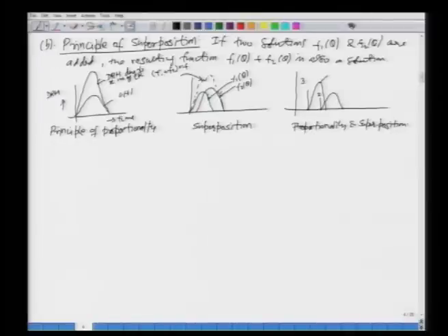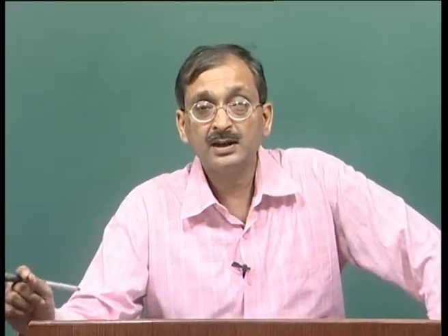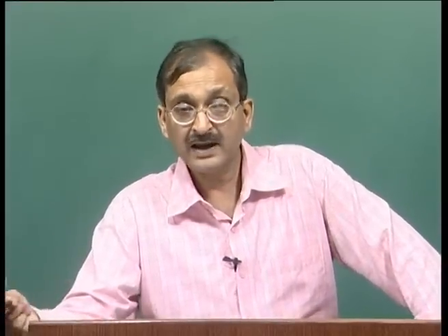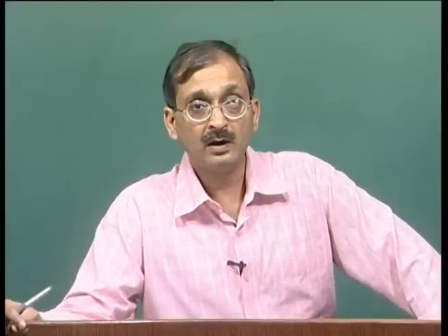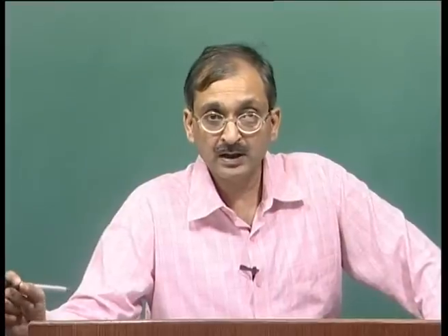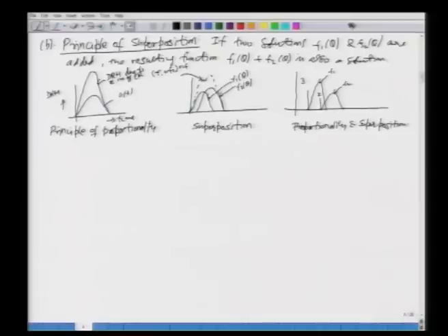So, now you have F1 and F2. What is F1? Well, F1 is the direct runoff hydrograph due to 3 centimeters of rainfall. So, F1 has actually accounted for the principle of proportionality. So, there is a unit hydrograph in the catchment, and then you apply that with a 3 centimeter rainfall impulse. That is what represents this F1 on this graph.